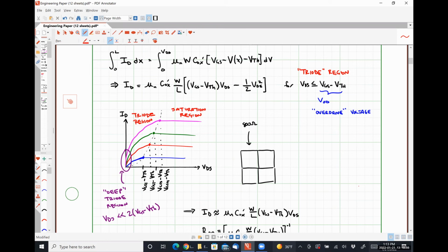Before we talk about that in terms of any math though, this curve looks effectively the exact same as a BJT, except the names of the regions are significantly different, which is absolutely something that can be confusing, right? So for a MOSFET transistor, when our current is stable and constant, we're in the saturation region. In a BJT transistor, we call this what?